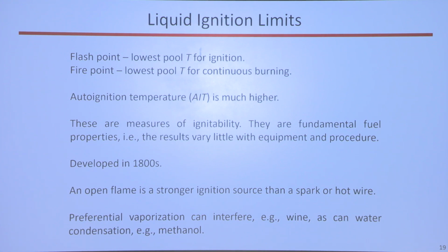A lot of times in combustion we talk about the AIT, auto ignition temperature, but this is a completely different test. It's a test kind of in a thermos. You drip a few drops of your liquid in, like gasoline with air, and you heat it up until you see fire shooting out the top. Auto ignition is a much higher temperature and an entirely different test. There's no pilot in an auto ignition temperature test. But both of them are measures of ignitability of liquids. They're both important to understand how those fuels burn and the fire safety.